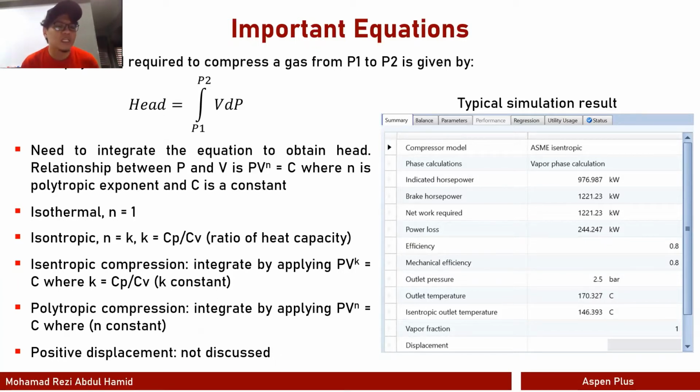We all know that compressor is basically a unit operation that would enable you to compress a gas by reducing its volume. And we all know that when we compress a gas, temperature also will increase because, assuming we have a gas and the gas undergoes, for example, an isentropic compression where the compression process occurs without any heat loss to the surrounding, the gas, basically your system, will be compressed.